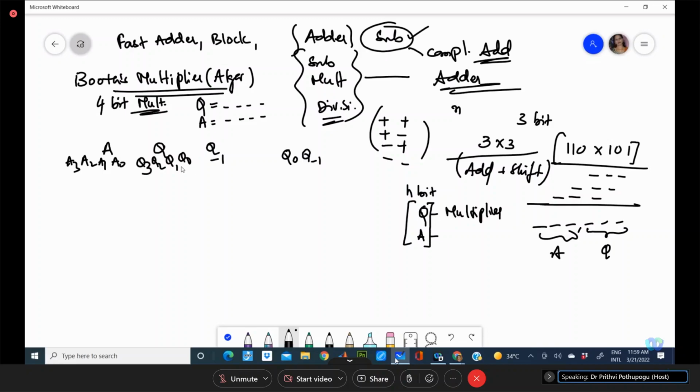Like we are adding 1 bit extra to the representation, initially we take this as 0. Then we do the arithmetic right shift. When doing so, this value will get either 0 or 1 based on the Q0 value. At a time we see the value of Q minus 1 and Q0.